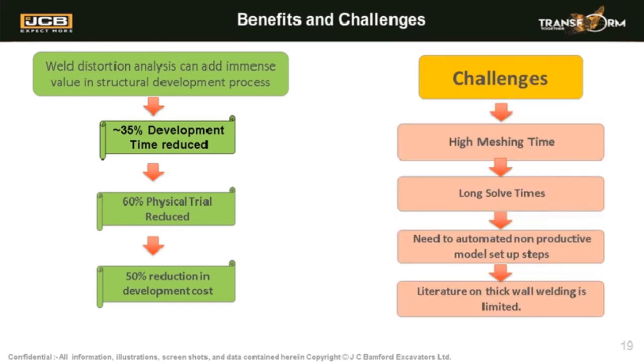On the challenges side, there are still some challenges to be faced. One is because you have to model in the welds, and there can be a lot of welds. If you look at the example of the cabin, for example, there can be a long meshing time. There can also be long solve times, although developments in high performance computing and cloud computing may well mitigate that.